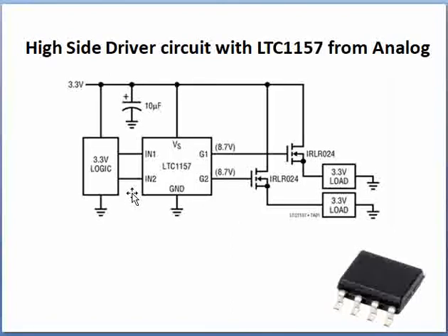So this is just to give a glimpse of how a high side driver is connected using LTC1157 from Analog Devices. It is taken from the Analog Devices chipset driver data sheet, where we have MOSFETs which are driven through the gate drivers. So the gate driver, LTC1157. You can see here this gate driver is driving the MOSFETs, and then you can see here this is a